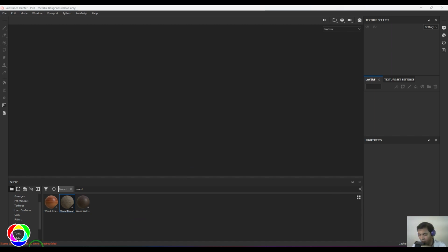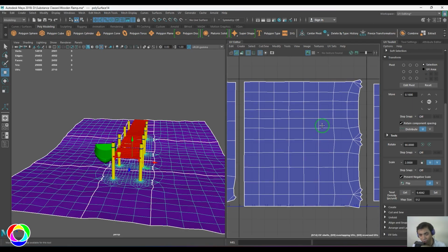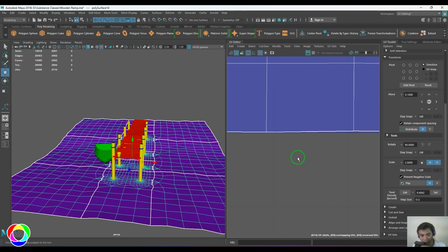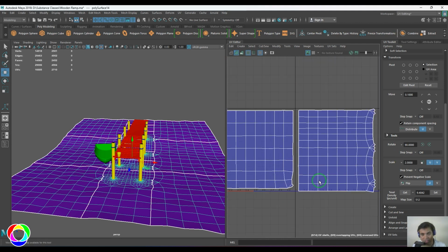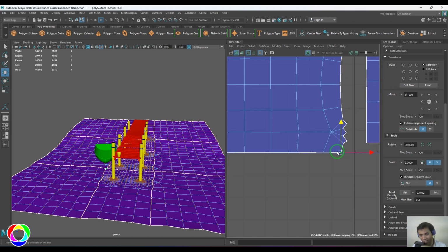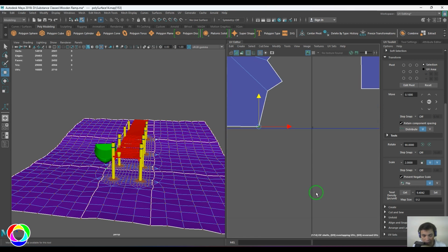So I'm getting an error here, and I just want to see what's the problem. So I'll go back to Maya, and then you should be able to see one of my UV shells is slightly off the tile, and it's there with this particular tile. So one thing I would like to do is compromise a little bit in the stretch. I just move this UV inside, or the other way is to scale it differently or cut a different seam line and all. So right now, just for a quick solution, I'm just moving it into the tile here.